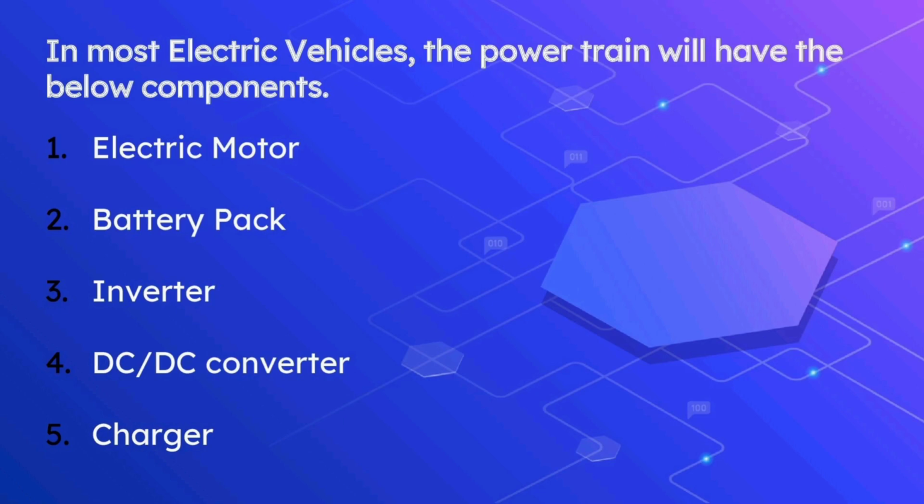Coming to the electric motor. It is an important part of electric vehicle powertrain development because it converts the electricity to torque to move the vehicle. The torque is controlled by varying the current flow. Its efficiency is above 90% as compared to an engine whose maximum efficiency is 40%. Electric motor provides torque at zero speed, so a single gear ratio can be used between the motor and the wheel. The motor is controlled by the electric vehicle motor controller.